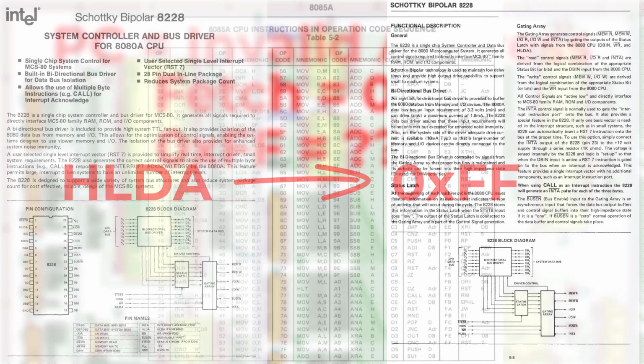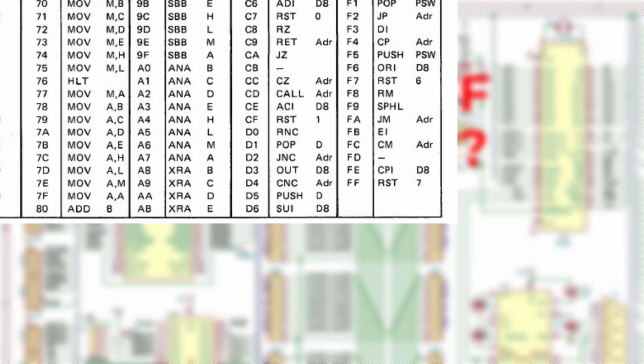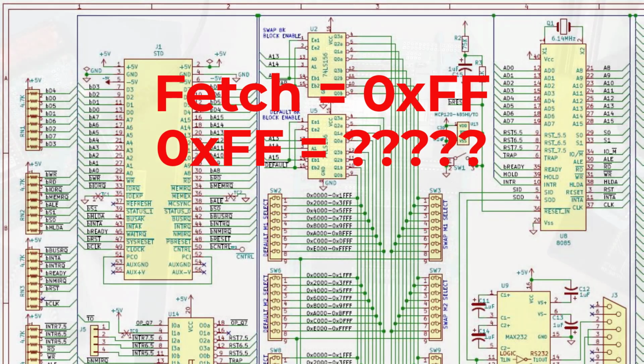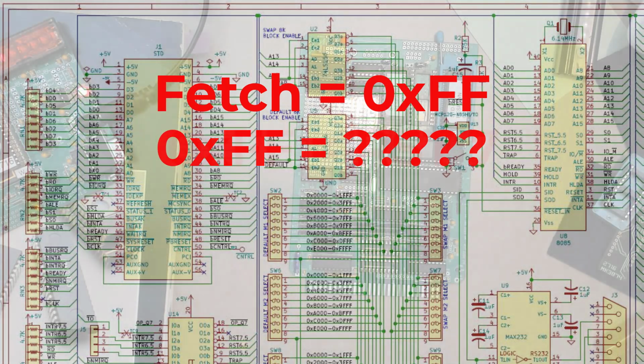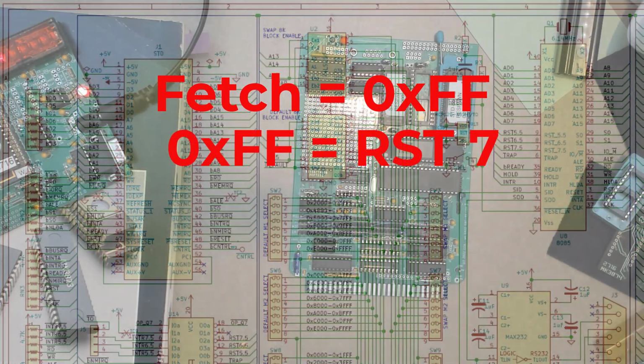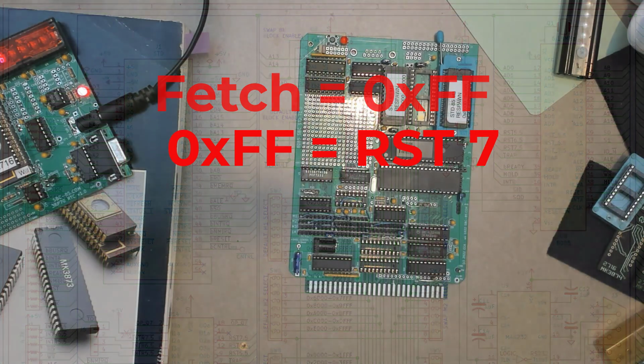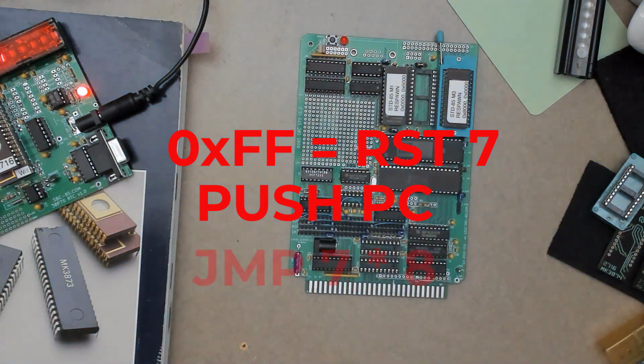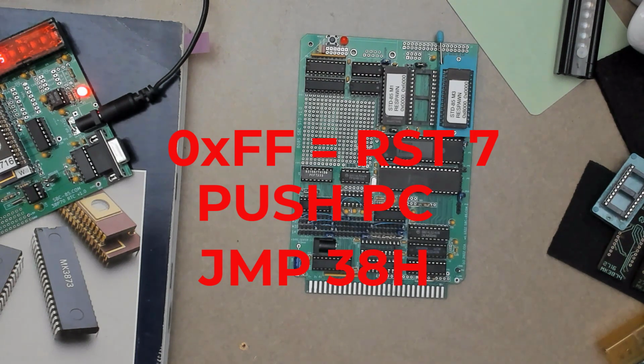So if we look up the machine instruction FF, we see that that is just a reset 7 to the 8080 or the 8085. So when it gets that FF off of the bus because nothing was out there in memory, it will execute a reset 7 instruction, and that causes the processor to push the current program counter onto the stack and vector to the address, which is 7 times 8, or to the address 56 in decimal, which, not surprisingly, is 38 in hex. So that's the respawn technique. No matter where your program dies, it will respawn at address 38.